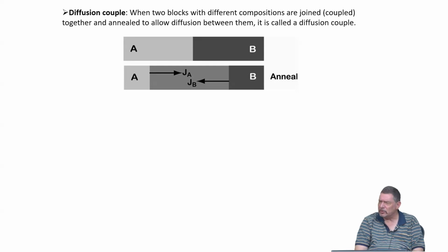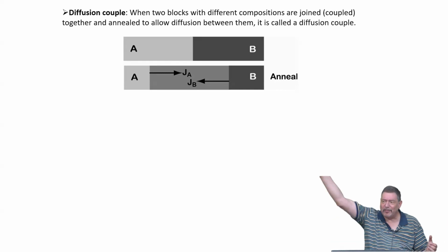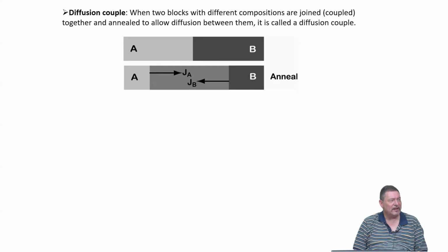Is there a solution for you guys? I mean, you cannot easily grab new equipment into your lab, right? So you're bound by what you have. But how would you conceptually improve the situation? So let's say after 10 hours annealing at 500 Kelvin, you don't get a result with your SEM, your scanning electron microscope.